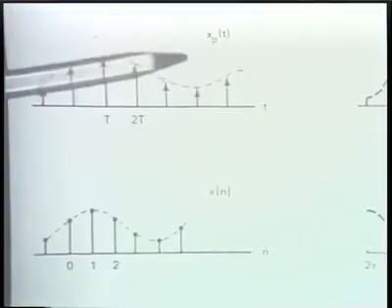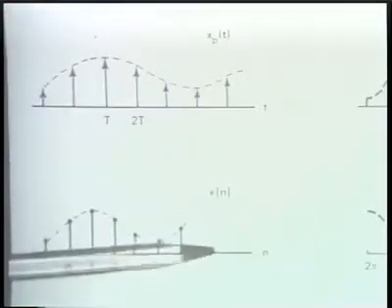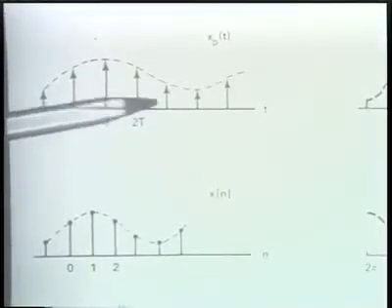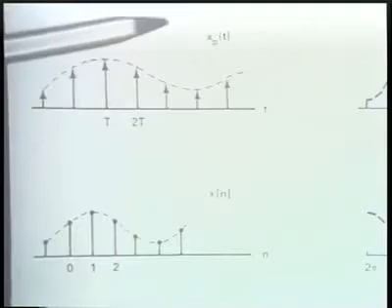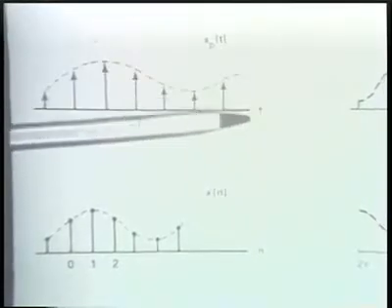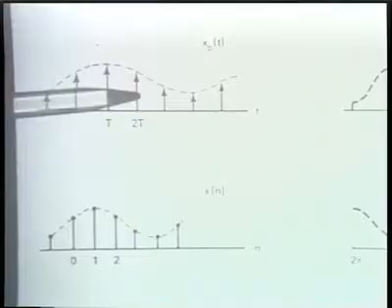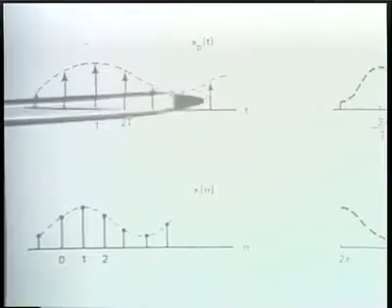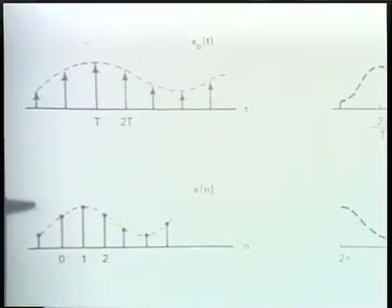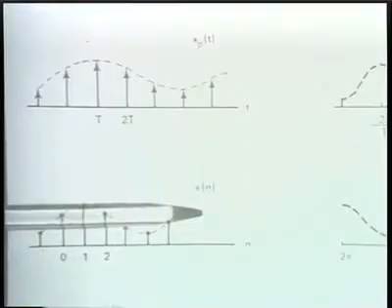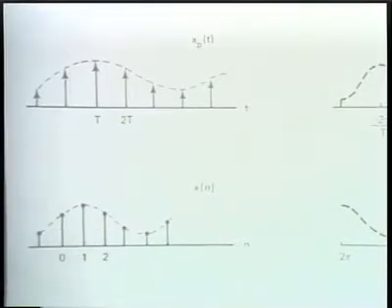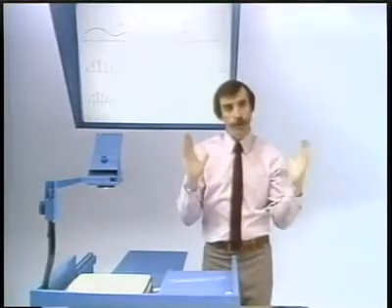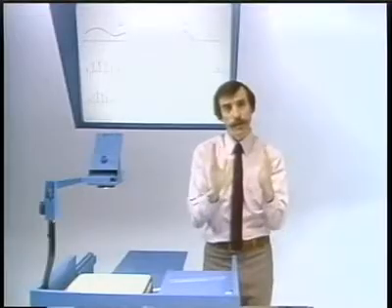So in effect, you could say that the step in going from here to here corresponds to normalizing out in the time domain the sampling period capital T. To stress that another way, if the sampling period were doubled so that in this picture the spacing stretched out by a factor of 2, nevertheless, for the discrete time signal, the spacing would remain as 1, and essentially it's the envelope of those sequence values that would then get compressed in time.